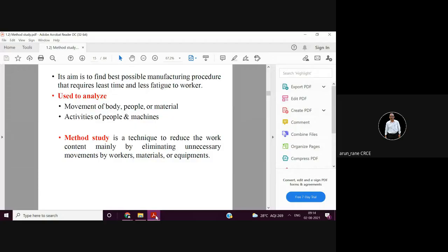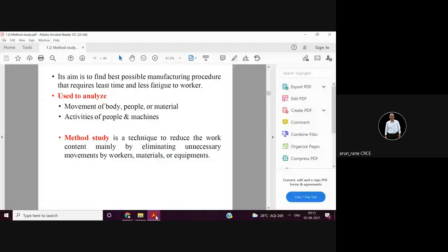So there the operator will be idle for 2 minutes, but the milling machine is taking 5 minutes. So all the jobs will get stuck at the milling machine. But you want a cycle time of 3 minutes. So what you can do in this case, there is no point in increasing the workers because one worker will work for one machine. So you can have two milling machines, that is, adding a parallel workstation. So with two milling machines, the time required at the milling workstation will be 2.5 minutes.